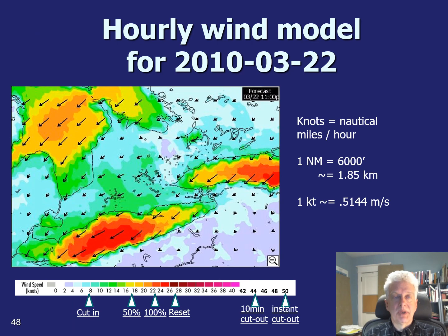So here's a wind map that I captured from 2010 when it was a really strong northeasterly wind. And an interesting thing you can see illustrated here is that the surface characteristics, the surface roughness, has a big effect on how much wind from a given airflow shows up down at the surface. So in cottage country up north of Toronto, the wind levels at the surface were quite low because the surface is quite rough there. Whereas over the Great Lakes, with the flat surface of the water, the high-speed winds that are aloft can reach right down near the surface, giving you very high waves on the lake. But if you had an offshore wind installation there, they would experience those really high winds.